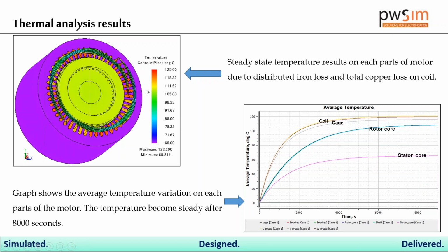This can give you a good understanding. If you see electric vehicle propulsion, for example, the motor design needs a good thermal analysis part. So whenever you design a motor, thermal becomes a very important, core part of the analysis. If the temperature goes beyond certain values like 120 or 150 degrees Celsius, the motor will fail to operate in a very short time, or the reliability of the motor will be very low in such conditions. That is where thermal analysis plays an important role in assessing the steady state as well as the transient analysis.